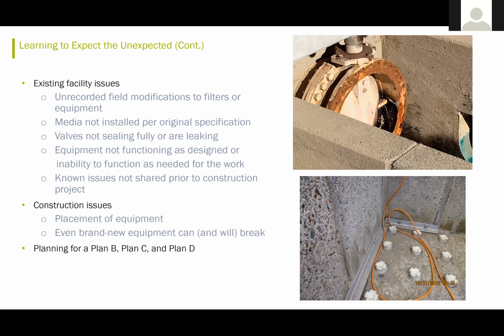There was some equipment that was not functionally designed, such as the air scour blowers. The programming on the blowers was incorrect, and the city had been able to kind of survive with some fairly poor performance. And there were some known issues that weren't shared with everybody prior to construction of the project.